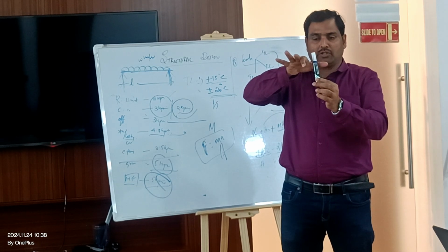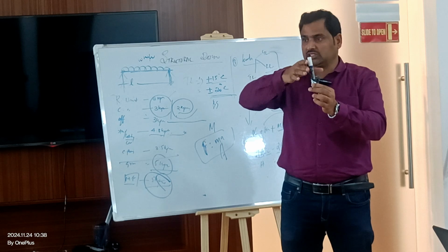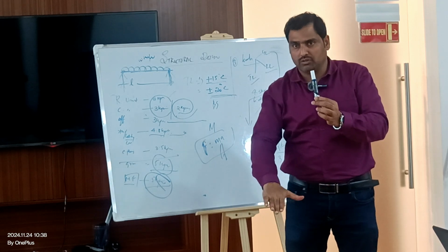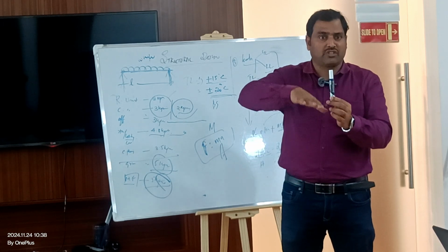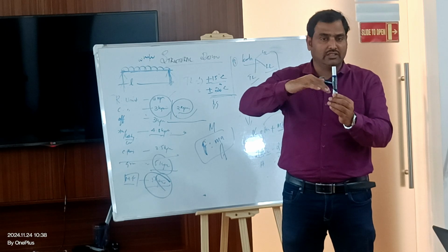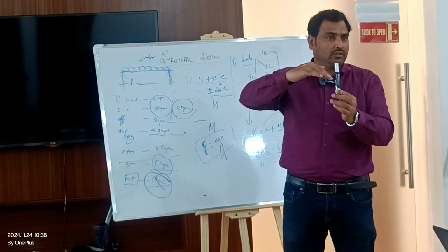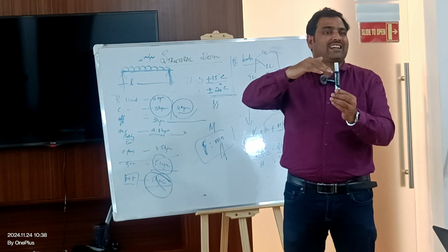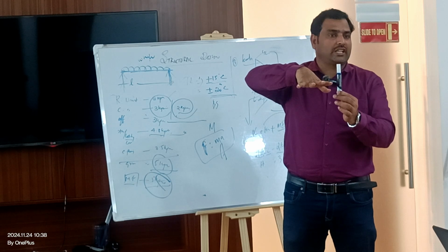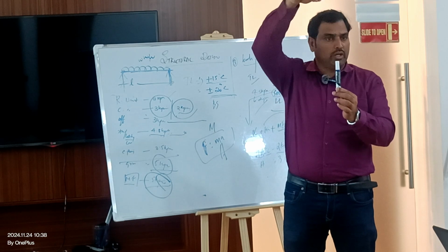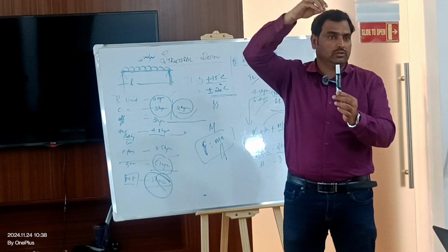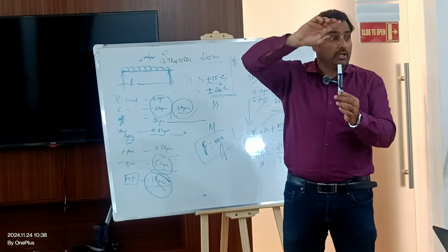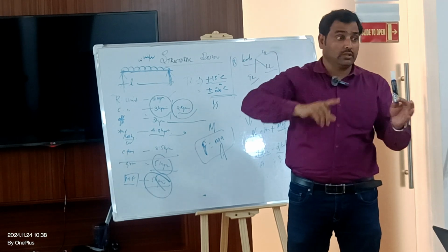When this slab and that slab touch each other, the cracks will start. But below 3 or 4 floors, you will not have such a scenario, because you will not have maximum drift or maximum temperature expansion. When going up, you will have huge drift, especially I'm talking about drift.